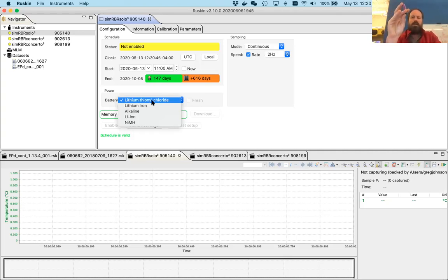of attitude problem. And the attitude problem is one which refers to the fact that lithium thionyl chloride batteries, when they are put in cold water or cold temperatures and kept very still, and have the positive anode facing down, the electrolyte can settle inside and it passivates over the anode, and you lose some capacity. And this can be very disturbing if you're doing an Arctic deployment, because you'll find that you lose 30 or 40% of your battery capacity.